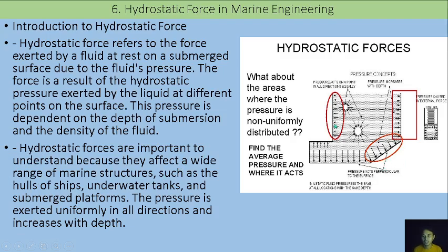So these are the hydrostatic force. Hydrostatic force refers to the force exerted by a fluid at rest on a submerged surface due to the fluid's pressure. The force is a result of the hydrostatic pressure exerted by the liquid at different points on the surface. This pressure is dependent on the depth of submersion and the density of the fluid. Hydrostatic forces are important to understand because they affect a wide range of marine structures such as the hulls of ships, underwater tanks, and submerged platforms. The pressure is exerted uniformly in all directions and increases with depth.